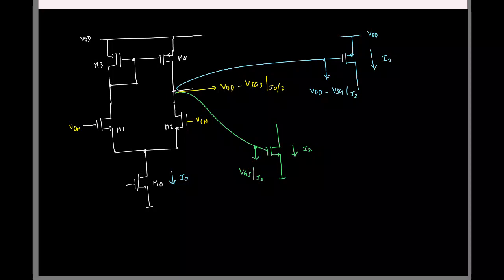So this stage naturally provides this voltage, and if you were to have an NMOS second stage, this seems to be the voltage needed, and for PMOS, this is the voltage needed. So what do you think is a better choice? PMOS, right? There is no harm in using an NMOS, but you need to make sure the levels are compatible. But if you have a PMOS, that's naturally compatible.